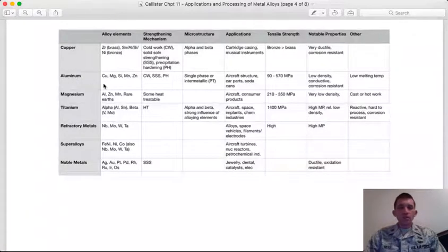To make aluminum strong enough to make, say, an aircraft out of, right? You add in these alloying elements specifically. I think copper is a big one. I think of that one as far as like 7075 T6, which is structural aluminum, or 2024 is also, I think, copper is one of the main alloy elements in there. Same thing with copper. You need the zinc, give you brass, or these elements here, tin, aluminum, silicon, nickel, to form bronze.